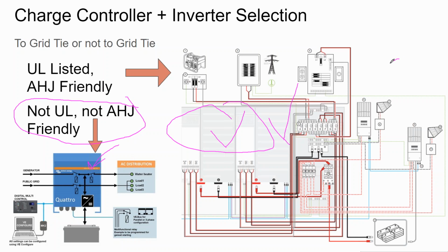It's the cost of this extra panel and the cost of these specialty breakers. What we're looking at on this panel on the right is actually both an AC and a DC panel, where the DC side is at the bottom, and these are all DC breakers, and the AC side's at the top, and it makes things kind of nice and neat and integrated.